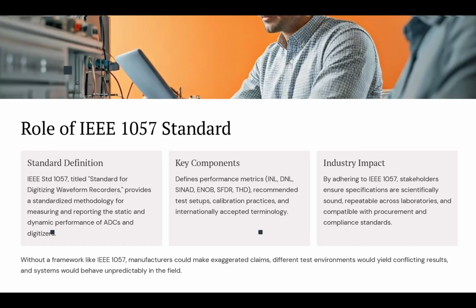Now, we said that each type of architecture has its own behavior and its own unique sensitivity. So when we want to test those, we have to go beyond the ADC types. We have to consider reference voltages, input signal purity, or clock accuracy. And environmental factors, because environmental factors actually affect the performance of the ADC significantly.